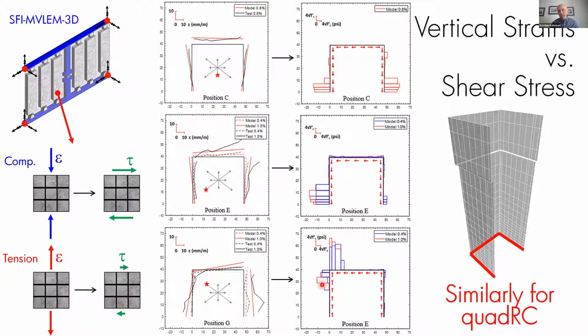So this is really interesting and important, actually, especially if you are someone who is doing analysis of core wall buildings or any kind of building that has a C-shaped or U-shaped wall like this under multi-directional loading. Because what this really means is that all shear demand is resisted only at those boundaries that are in compression, and the tension side of the wall is really not resisting much shear.